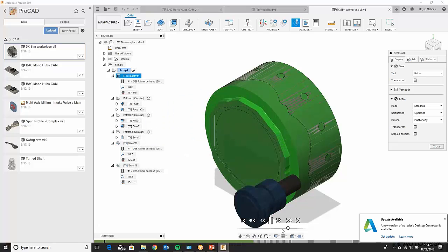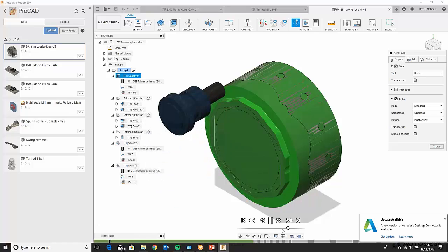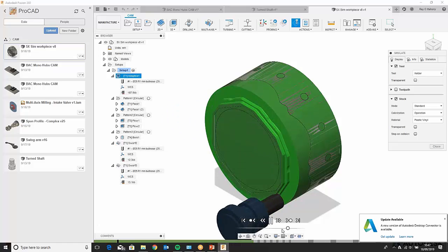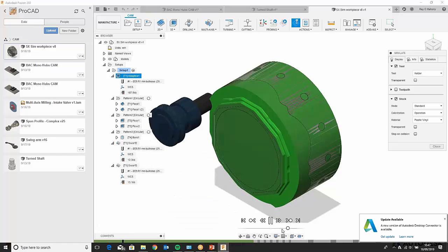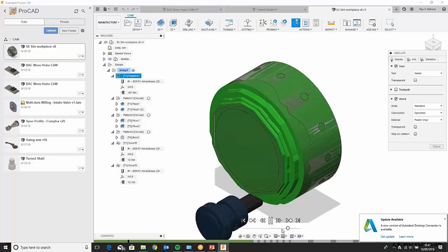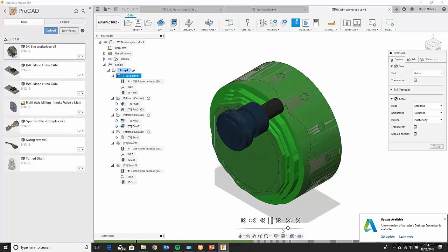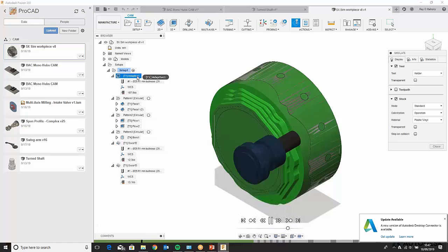You can see the machine strategy. It's very much like a polygon, an 8-sided polygon that we're trying to machine here. So you can see the tool is targeting itself to make sure that it meets all that area and that area and the corners, and you can see it's stepping as well. We can even control the step sizes, the finishing, the roughing, how smooth we want to finish it out, if necessary for you to polish as well. So in this case, you can see we're still in the adaptive process over here, and this should move on pretty quick in a second.